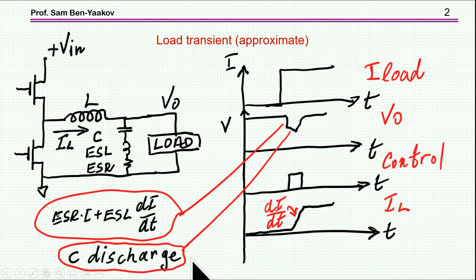I'm showing here a buck converter, which I'm assuming is used for a server in which we have a high voltage, say 12 volt, and there is a need to get 1.2 volt at the output. So if this would have been one stage, and we have a load, which would be like a heavy microprocessor, then we have an inrush current, that is the processor was hibernating and then it starts running. There might be a step here of the load of very high current, could be a few tenths of an amp, depending on the system.